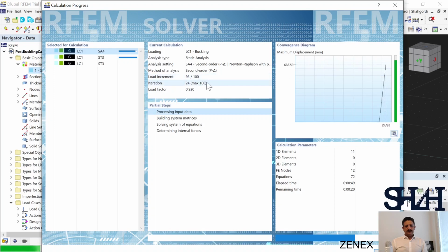Now, here we can see that in the 93 iteration, it cannot converge in the iteration, and it goes to the maximum. If we change this maximum iteration to even 500, I don't think that we will have the convergence because it is not. So after that 93, the results might not be reliable because it is just 100 times iteration and the results would not be valid. And we cannot confirm with our calculation.